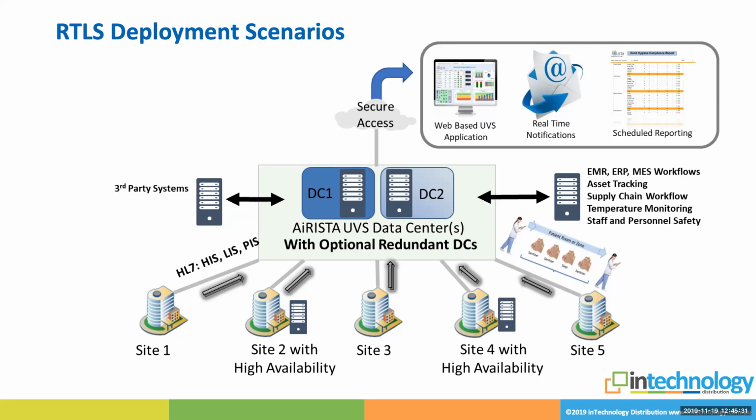Okay, great. Another question: is there a limit to the amount of tags that can be within one facility? What the question is really saying is, is there a limit to the amount of tags that can be run over their Wi-Fi network, and does it actually interfere with their other Wi-Fi infrastructure that they're currently working with? It would depend on the total number. For asset tags and the like, most location is done in a blink mode where there's really not much of a limit. In fact, the base server configuration is configured for 20,000 tags in a facility.